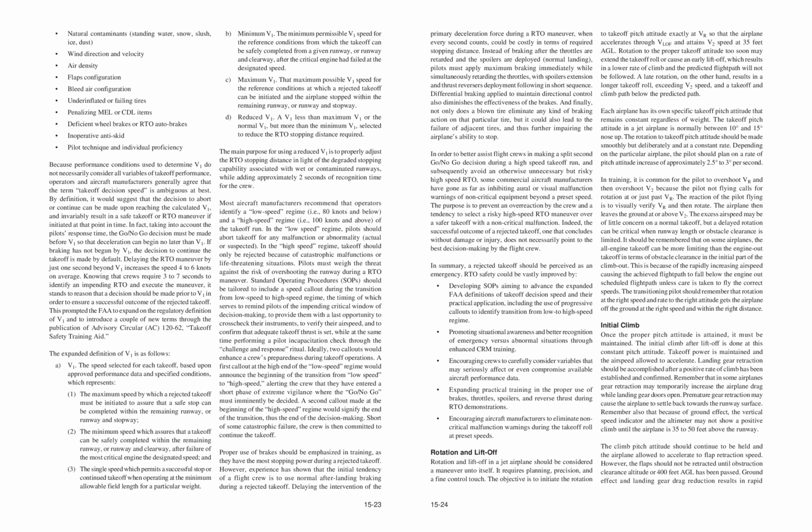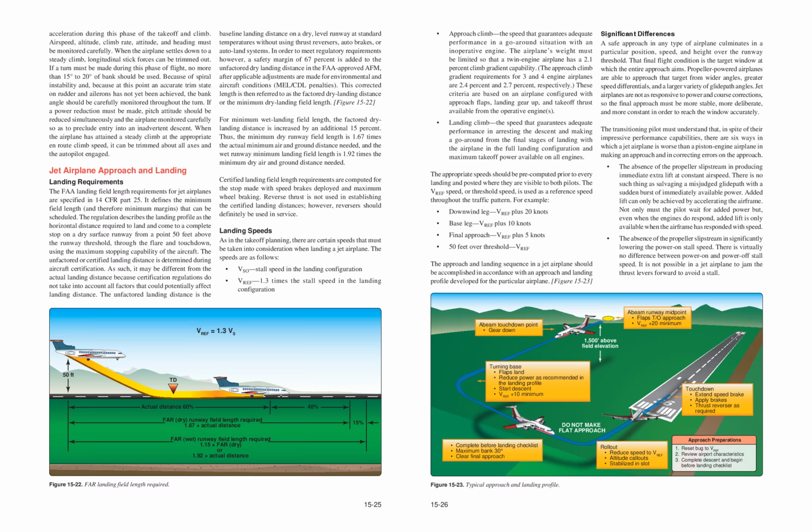Ground effect and landing gear drag reduction results in rapid acceleration during this phase of the takeoff and climb. Airspeed, altitude, climb rate, attitude, and heading must be monitored carefully. When the airplane settles down to a steady climb, longitudinal stick forces can be trimmed out.